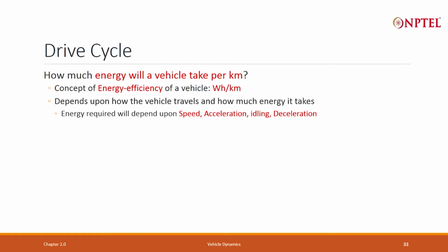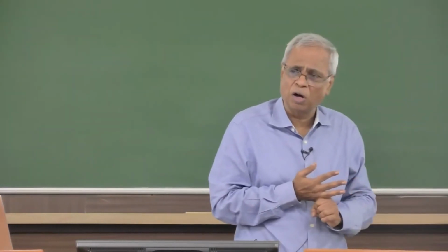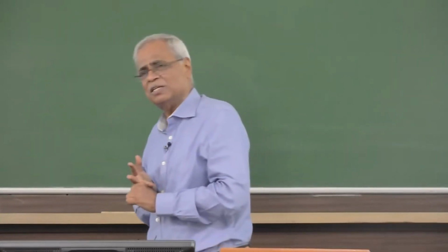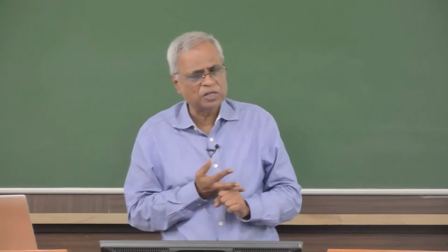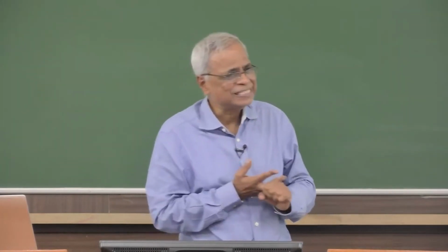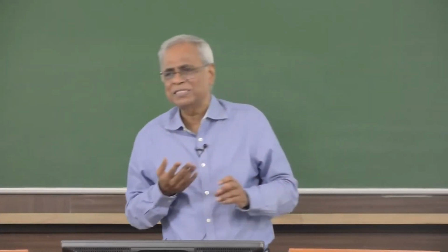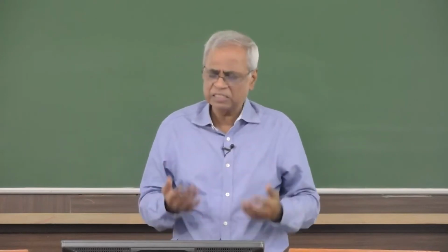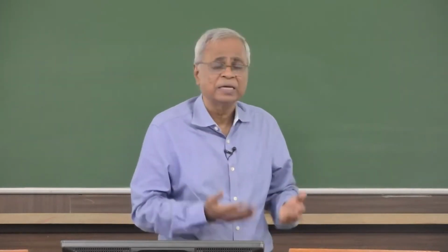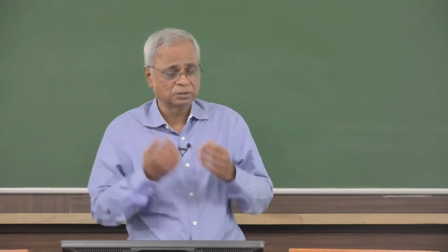When it decelerates, it gives you back some power, energy, but only a fraction of the energy. So, at what speed you travel, for how long, what is the acceleration, for how long, from what velocity to what, how much do you decelerate, for how long, how much are you idling, all these things become an important component in the amount of energy consumed.